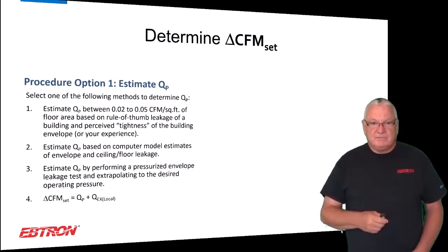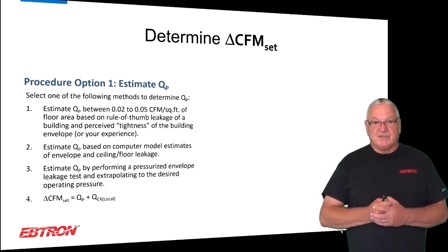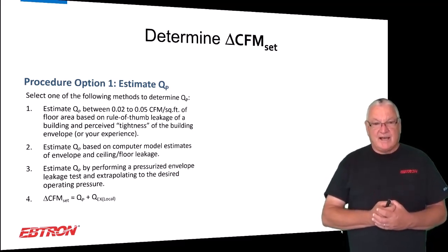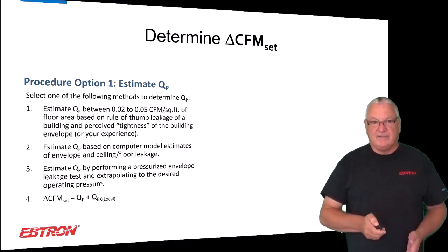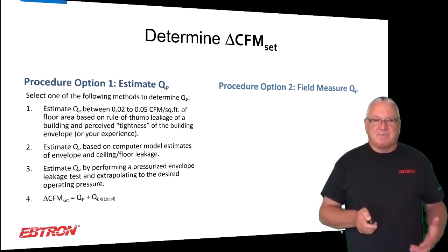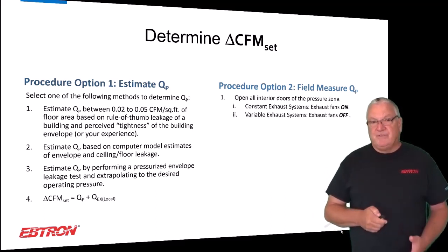But whatever it is, the bottom line is your set point is equal to whatever pressurization flow you figure out, calculate, and any local exhaust you have. So that's procedure one, okay? That's option one. Option two would be to field measure it.